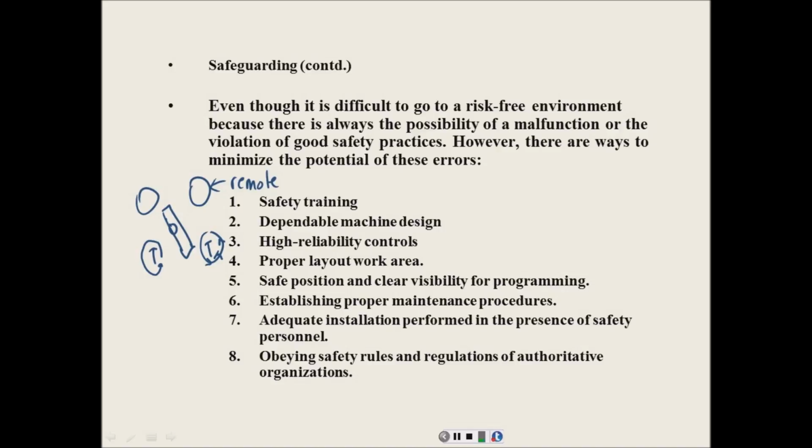When y'all saw me move the big Fanuc for you in here, that was high speed teach. When I jogged it, it was still 25 millimeters per second, but when you saw the robot move, it was running at full speed. But I had the teach pendant in my hand with the emergency stop, and the dead man switch was in. So if somebody had jumped out there, all I would have had to do was release it, right? We don't run that thing in auto mode because it's not safeguarded.